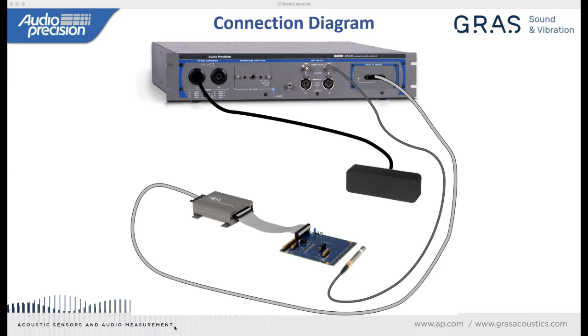Now, 1/8-inch microphones do have the property that their sensitivity is even lower. They can have sensitivity even below a millivolt per Pascal. So that introduces some other challenges, but they definitely do exist. And if you need to measure to high frequencies, you may find some utility in all of that.